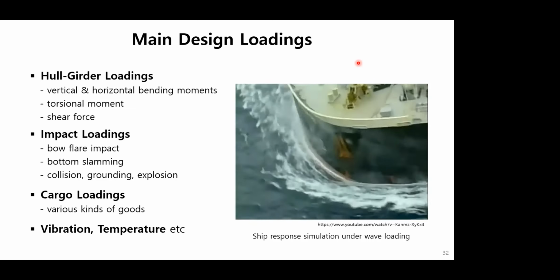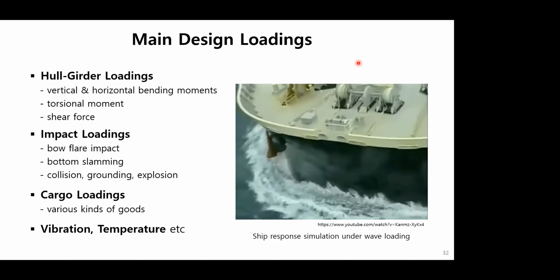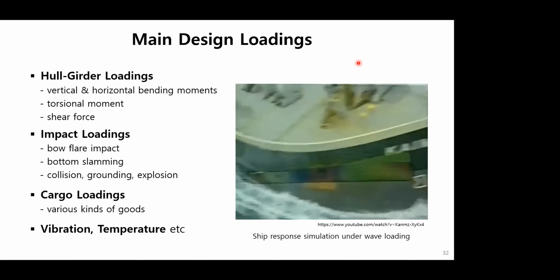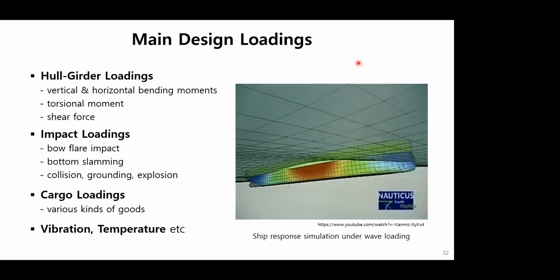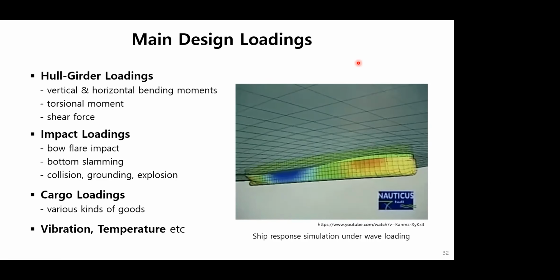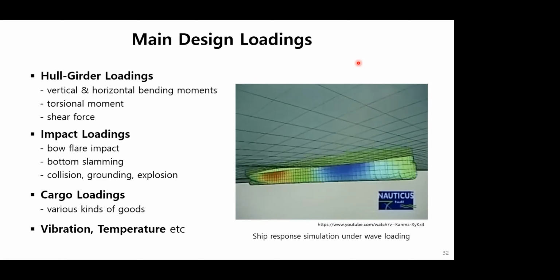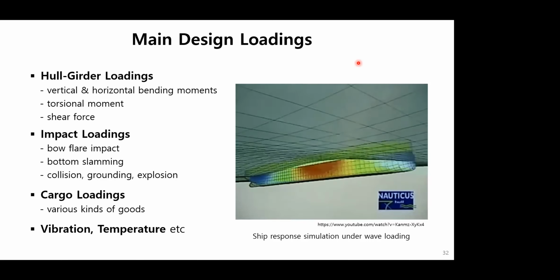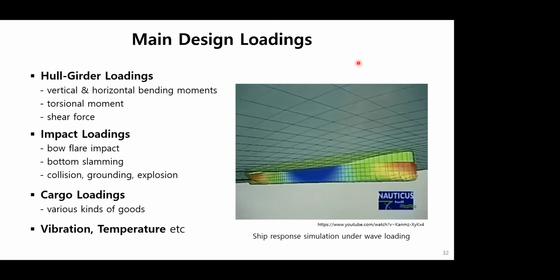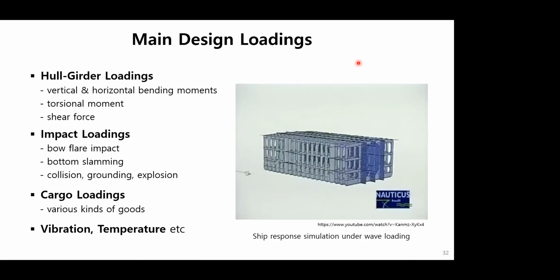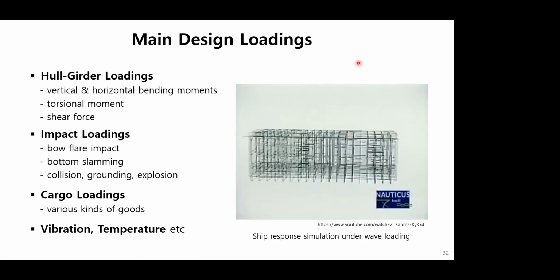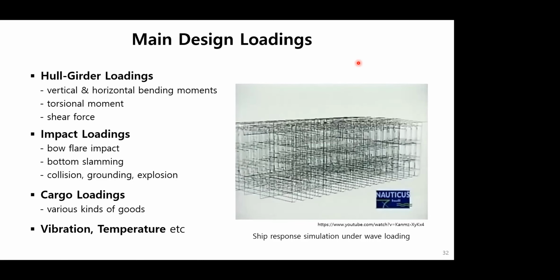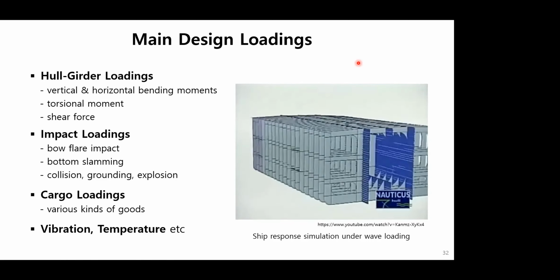So at sea, the ship's hull is continuously being exposed to a large number of forces coming from practically all directions. The same simple beam principle also occurs in complex combinations inside the ship's structure, where plating, frames, stiffeners, girders, panels and brackets are built up from many separate small beam elements, all working together.